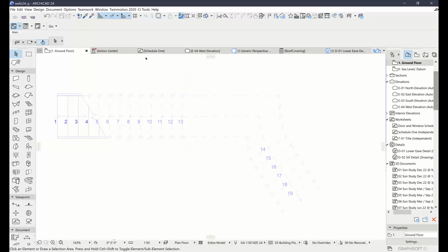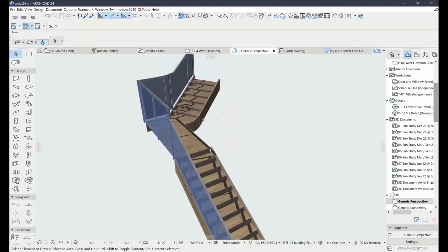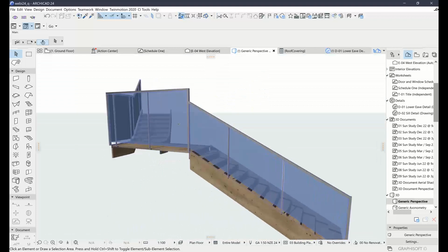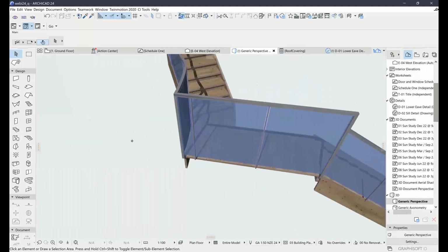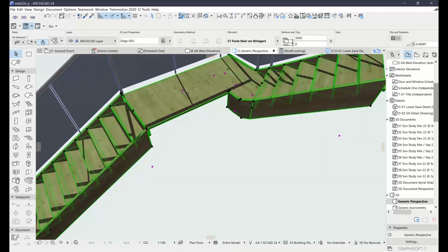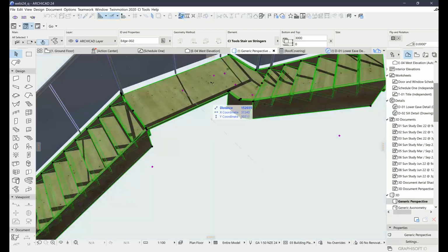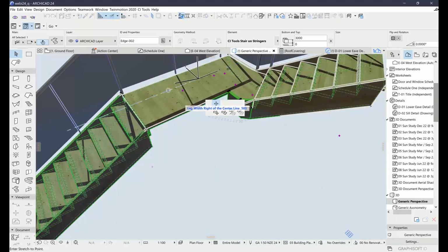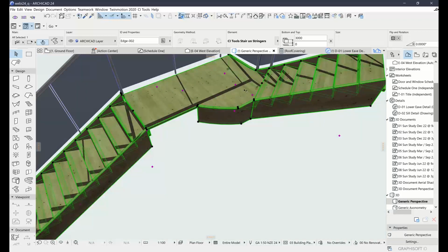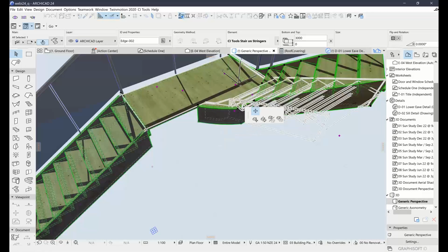And any changes that you make, there's my 3D view, will also be automatically picked up by the railing as well, because it's just attached to the stair. So it'll adopt any of those changes that you make, and you can also make the changes while you're in 3D as well. So if you select the stair here, you can see the same controls. That's the curve one. That's the leg width, which I adjusted just before. All of the same settings that you could see before. That one's a little bit tricky because it is on the short edge.